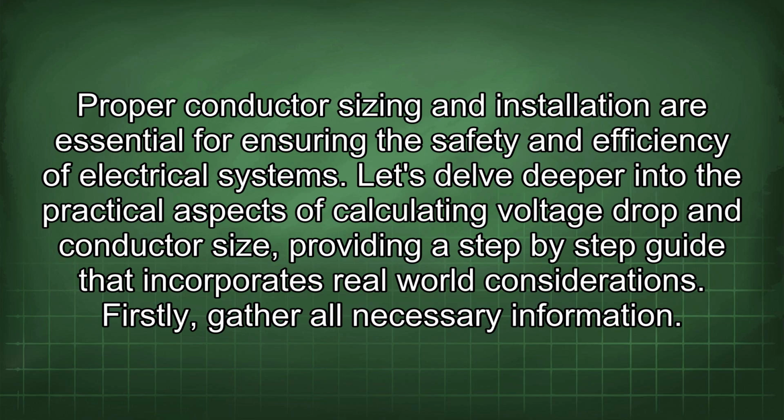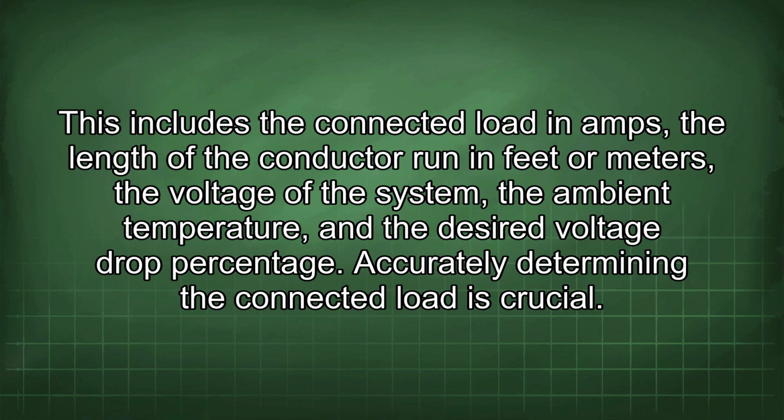Let's delve deeper into the practical aspects of calculating voltage drop and conductor size, providing a step-by-step guide that incorporates real-world considerations. Firstly, gather all necessary information. This includes the connected load in amps, the length of the conductor run in feet or meters, the voltage of the system, the ambient temperature, and the desired voltage drop percentage.